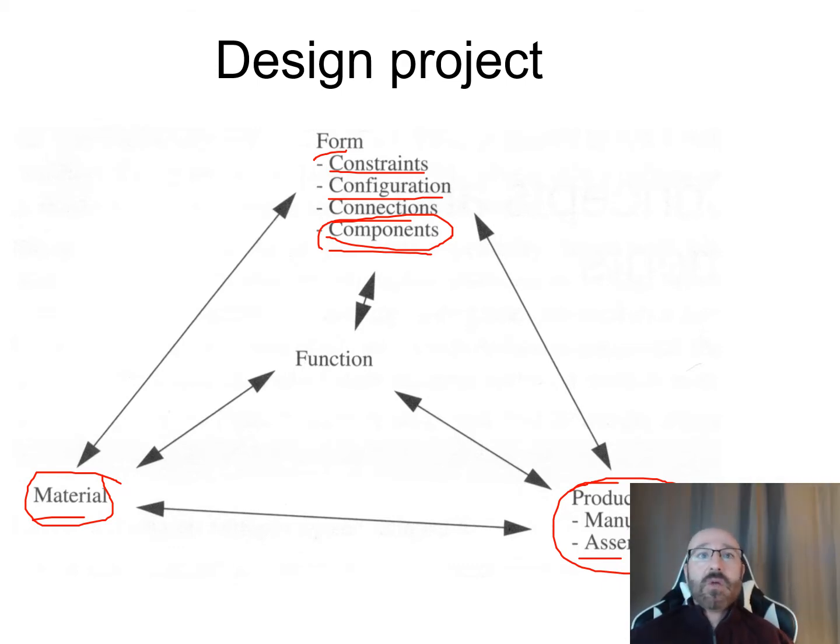So let's just say we choose a stainless steel buckle. What type of manufacturing process are we allowed to use for something that needs that level of detail, and the small machining processes associated with the features of that in a stainless steel? What things can we utilize for stainless steel there? Whereas if instead of stainless steel, we decided to go with plastic, all of a sudden we have different types of production. We could do some 3D printing, injection molding, things like that we couldn't necessarily do if we were dealing with stainless steel.